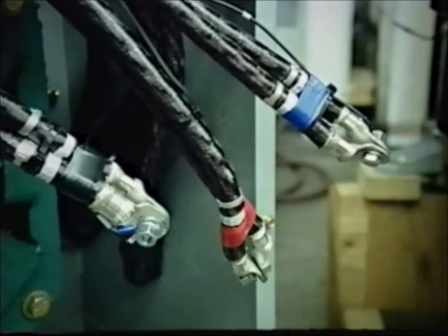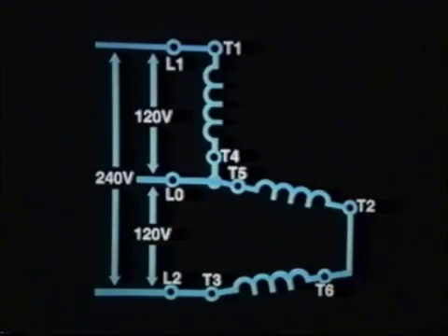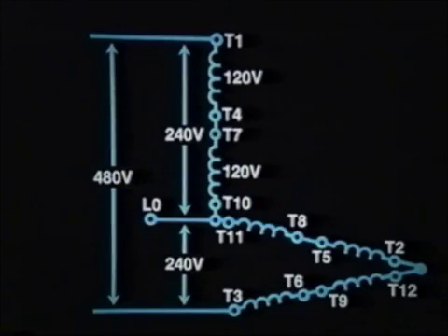Three-phase armatures may be reconnected to a single-phase armature if all the phase coil group leads are brought out to the connection box. This connection is called a single-phase zigzag connection or an open delta connection. A 12 lead wire alternator may be zigzag connected for 480 volts single phase.